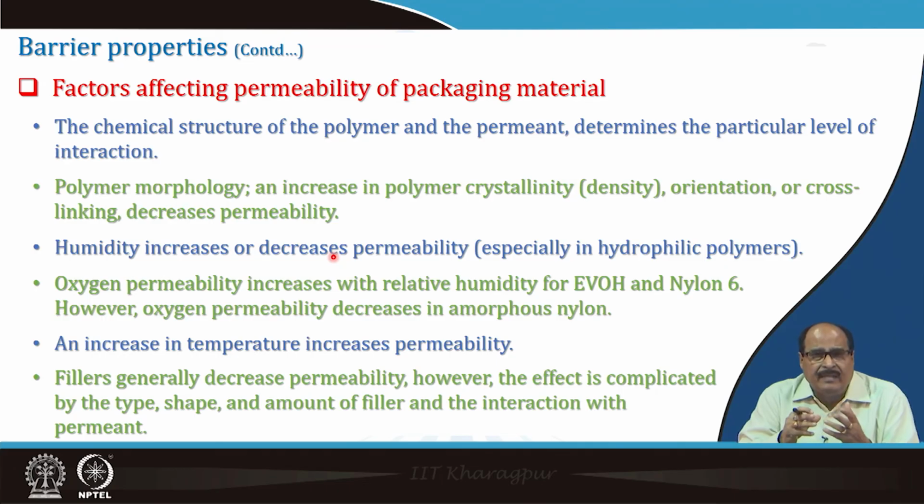Humidity increases or decreases the permeability, especially in hydrophilic polymers. Oxygen permeability increases with the increase in relative humidity for EVOH or nylon 6. However, oxygen permeability decreases in amorphous nylon, and an increase in temperature increases the permeability. Fillers increase the permeability. However, the effect is complicated by the type, shape, amount of filler and the interaction with the permeant.